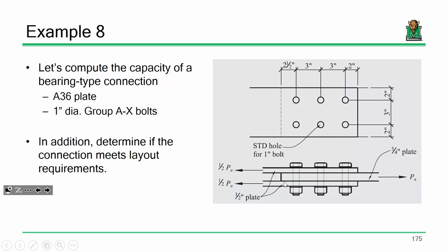So help me out. We in single shear or double shear? Double shear. There we go. All right, so we got a double shear connection. We've got 6 bolts. Now, you're really going to want to pay attention to your spacings, because if you look, one of my edge distances is going to be 2 inches, but another one is going to be 2.5. So this just becomes a bookkeeping issue, making sure you're clear on that. Okay, so we've got A36 steel.